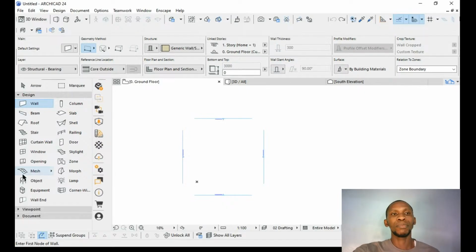Right, so now we have the wall tool, and for this wall tool the settings are displayed here. So let me click on this small arrow here and double click on it. What happens? It pops up this window. Under this window, I have model, geometry and position. So I can set the height of this particular wall. Let me select not linked. I can make the wall height 3,300 millimeters, and the base offset is zero, so it starts from floor level zero.